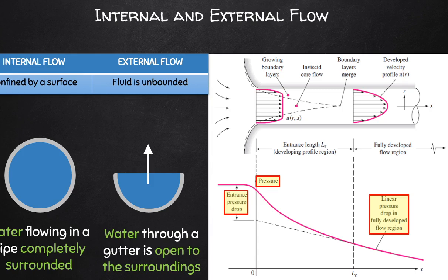And this reason becomes apparent when you plot the pressure against the length of pipe as shown here. What typically happens is that as the flow enters the pipe, there is a marked non-linear pressure drop at the entrance, and then once flow is fully developed inside the pipe, the pressure drop becomes more linear and can be described quite easily using the Darcy-Weisbach equation that we have in any case been applying to piping system design.